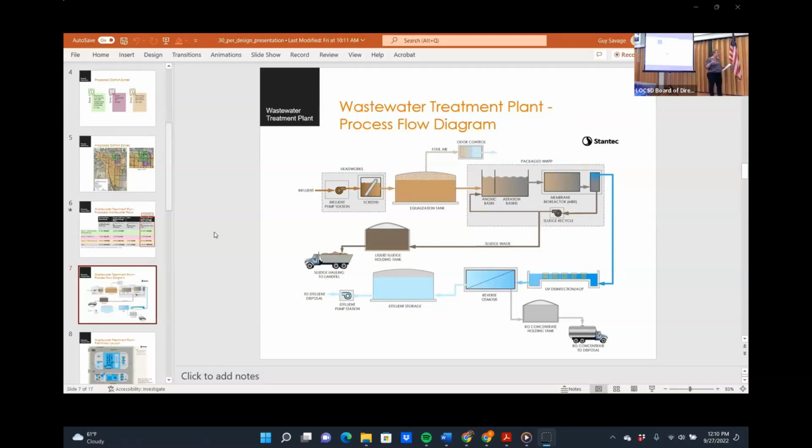You're able to control your flow, and you're able to understand what your tolerances are. With wastewater, you can't shut it off. There is no way to shut it off. Right? You're going to continue flushing. So you have to have a size that can capture those max flows. So that's one component. And then that goes into an equalization tank, and that's where it starts mellowing out those diurnals, and you're getting more of a constant flow that you can pump into your system or flow through your treatment plant.